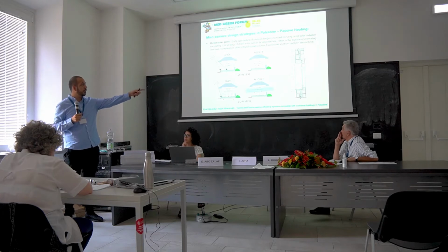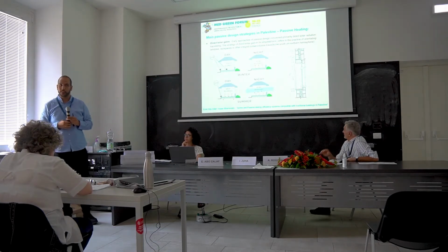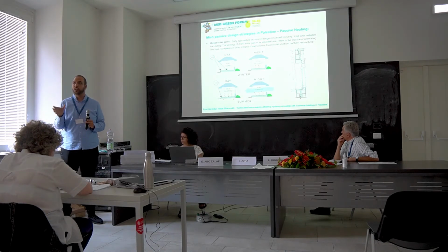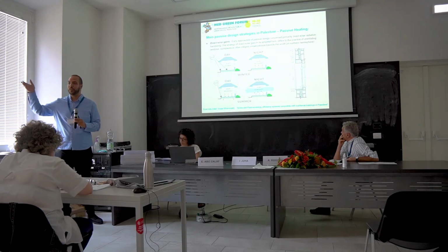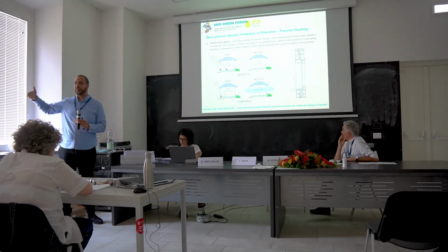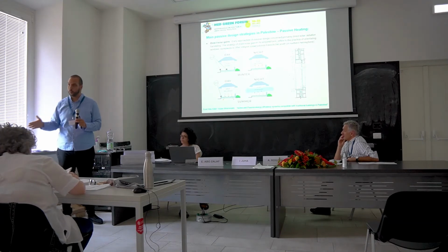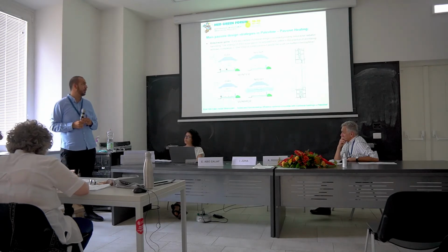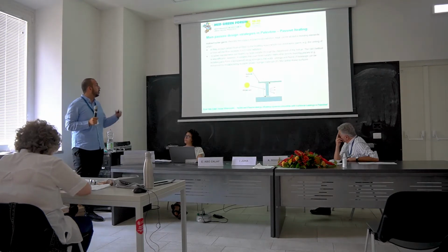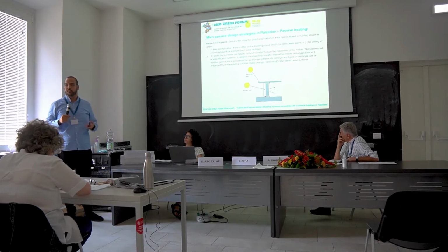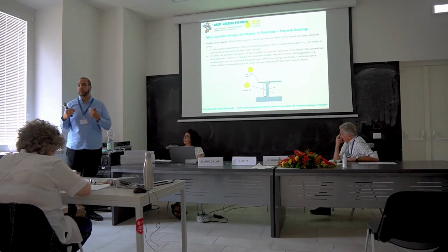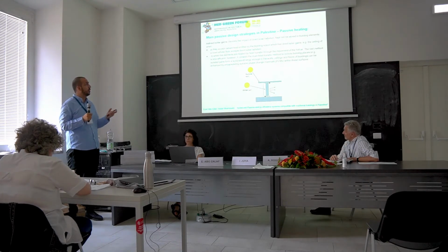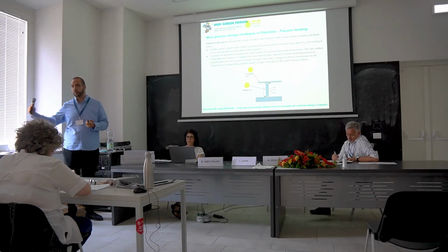I put the window section here with the wall to explain that in the heritage building, because of the thickness of the wall, they had already achieved 50 to 60% of the shading elements, because the sun in summer can enter only 1 meter inside the house. So with a little help from us with the shading, we can achieve the maximum. And also the indirect solar gains, which is the same as before: you heat an element from outside and then let the energy go to the building. It's either slabs on the roof, or walls, or windows, etc.